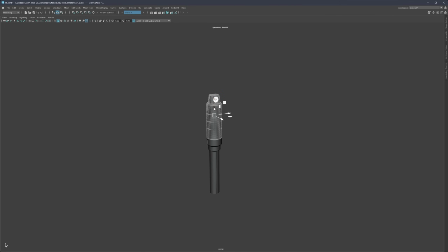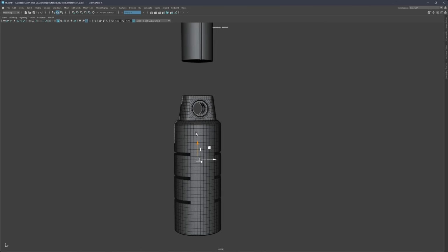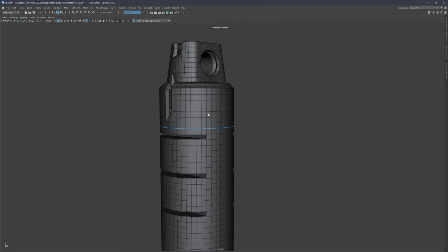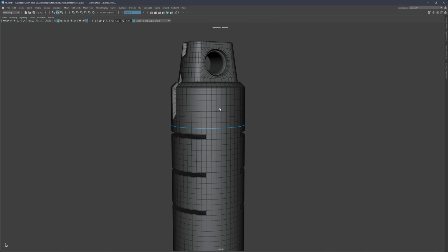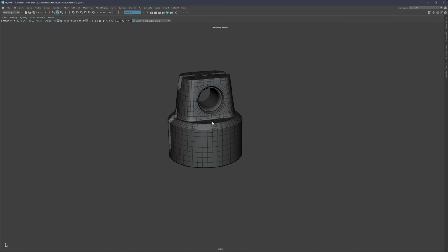So move mode, and then we're holding shift. Let's just clone this together, and here I just need to be sure to not use everything, maybe till here. So let's double click on this edge, and then let's simply go to shift, right click, and then again detach. And like I mentioned before, what this will do is just now detach top and bottom parts, and then the bottom part we can delete.